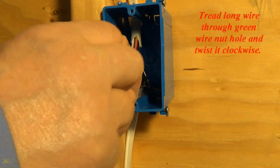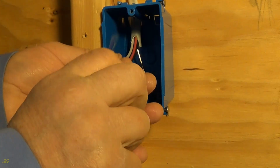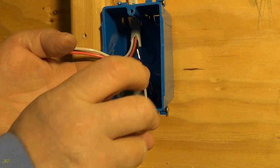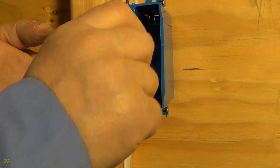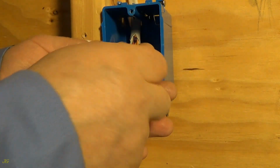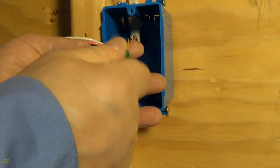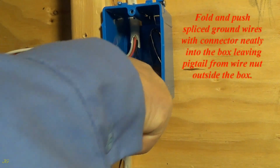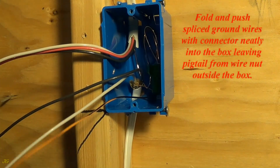Thread long wire through green wire nut hole and twist it clockwise. Fold and push spliced ground wires with connector neatly into the box, leaving pigtail from wire nut outside the box.